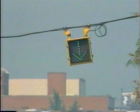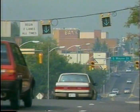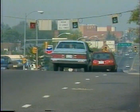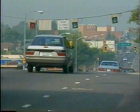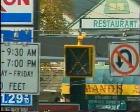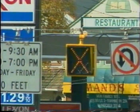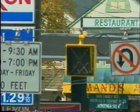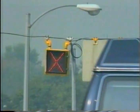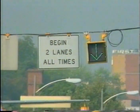There are three conditions of these signals: a steady, downward green arrow on an opaque background, which means drivers may drive in the lane directly beneath the signal; a steady yellow X, which means drivers should prepare to leave the lane directly beneath the signal; a flashing yellow X, which means drivers may use the lane directly beneath for a left turn only; and a steady red X, which means drivers may not drive in the lane directly beneath the signal. The signals are located over the center of each lane.